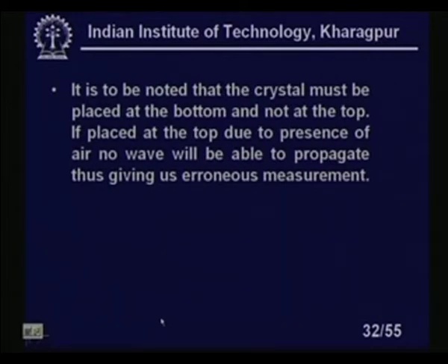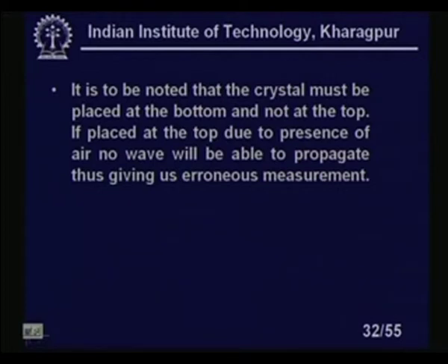It is to be noted that the crystal must be placed at the bottom, not at the top, just as we have discussed right now, right. If placed at the top, due to the presence of air, no wave will be able to propagate, thus giving us erroneous measurements, right. That is the reason we have installed it at the bottom of our vessel.